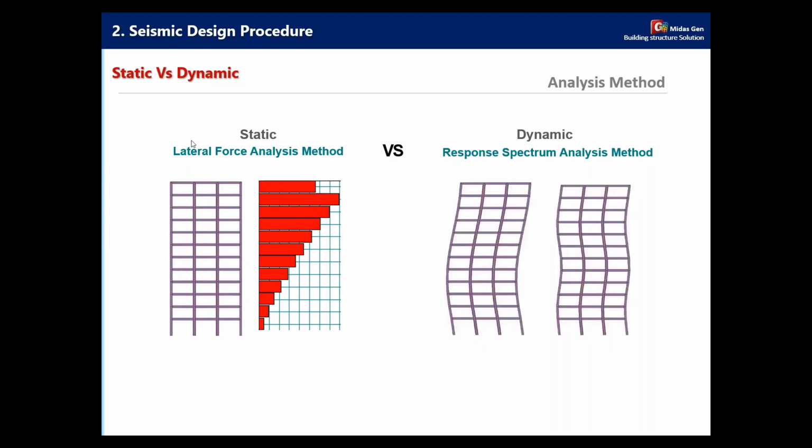The lateral force analysis method is a static method, and we calculate the seismic load using the base shear. For the response spectrum analysis method, we use modal response to calculate the seismic force, the seismic load.